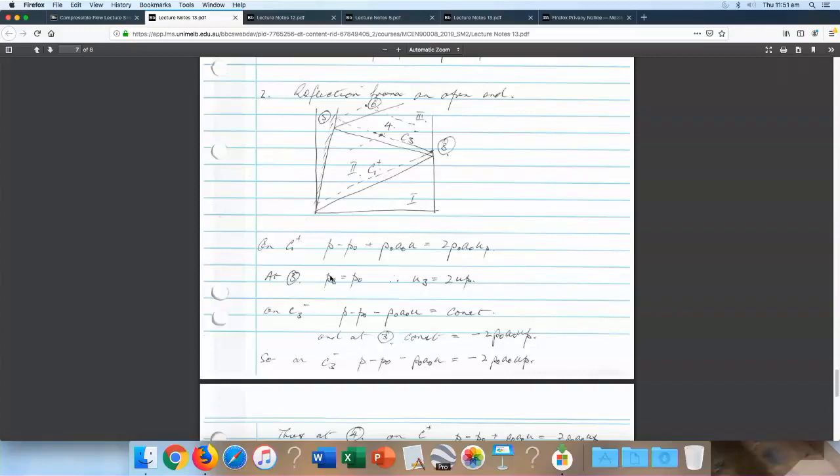I increase, here my plate downstream is hinged here, and I'm going to deflect it a little bit. Then I'm going to deflect it some more. And then some more. What? Beg your pardon? It'll detach? Correct. You'll go from the weak solution, which is the supersonic flow downstream, to a strong solution, and you'll probably get subsonic flow. And the most likely subsonic flow is somewhere a normal shock, just by the symmetry of the problem. Now, that may not be the case.